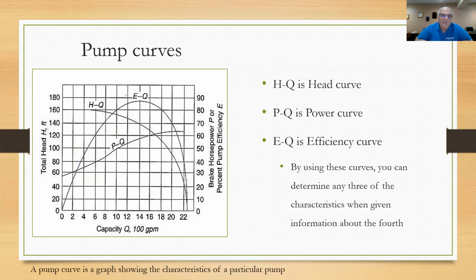On either side of that line, at 1,200 gallons per minute or 1,600 gallons per minute, I'm not as efficient. So if this pump doesn't put out 1,400 gallons per minute, there's more wasted energy. There's more inefficiency, and that would play into your horsepower equation. And we'll do that on the next presentation that we do.